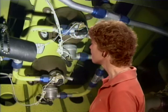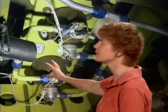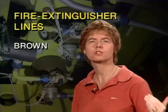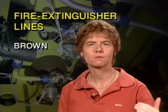Now, for a fire extinguishing system that has been discharged, if it uses a Freon agent, the maintenance you have to do is purge the system with air and replace the container. And by the way, you need to know that fire extinguisher lines are color-coded brown.